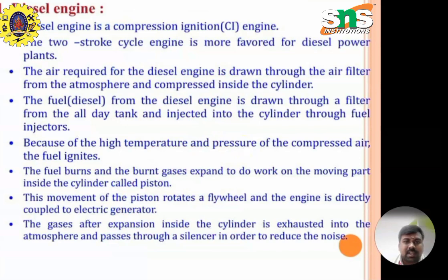A diesel engine is a compression ignition engine. The two-stroke cycle engine is more favored for diesel power plants. The air required for the diesel engine is drawn through an air filter from the atmosphere and compressed inside the cylinder. The fuel, that means diesel, is drawn through a filter from the all-day tank and injected into the cylinder through a fuel injector.